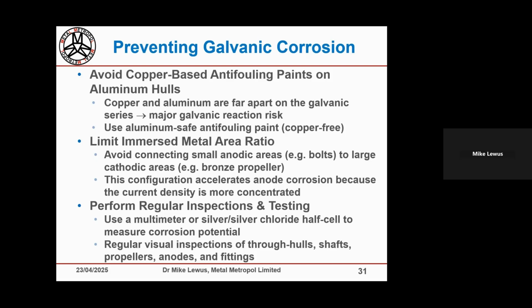It's more intermetallic particles at the surface, and once those have gone, the aluminium repassivates. But generally the conventional thinking is keep copper-rich paints away from aluminium. That's something we could discuss in more detail at another time.